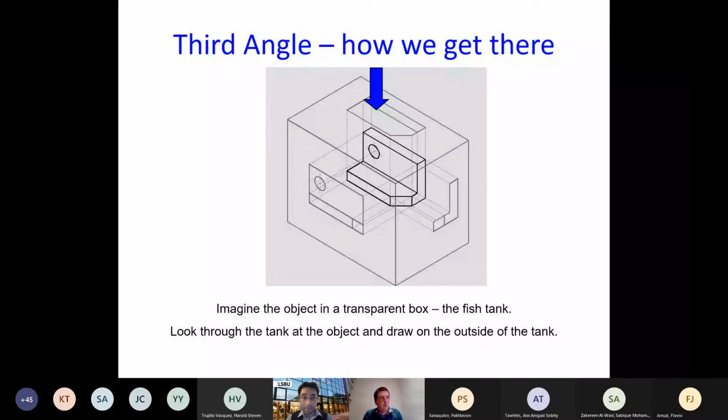I think in the demo we're about to start, everyone, we'll remind you how to change the standard view in Fusion to third angle projection. It won't take long actually to then do another version of that drawing, and we could actually create it in first angle, just so you can see a little bit of the differences.